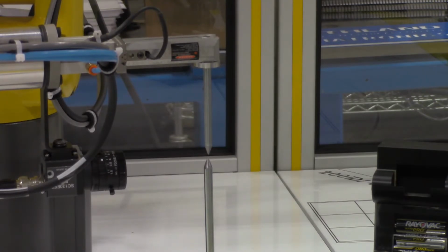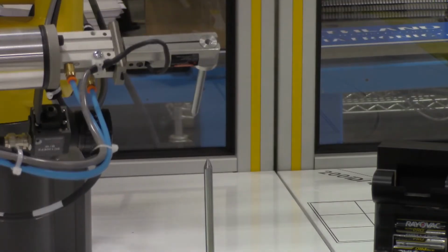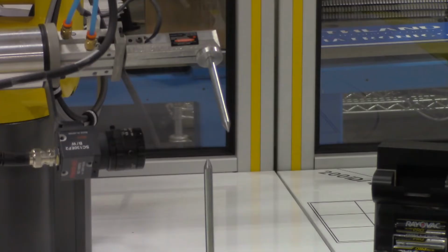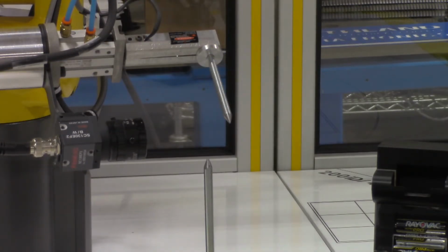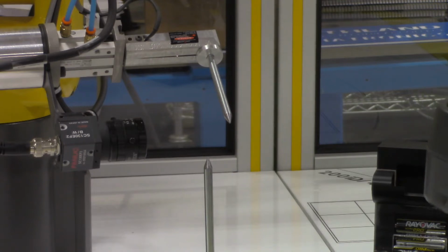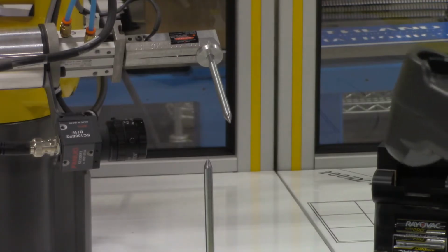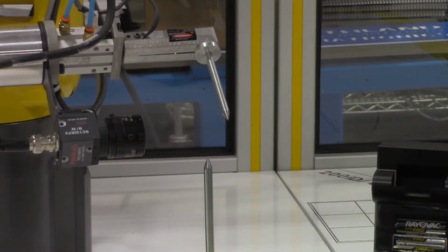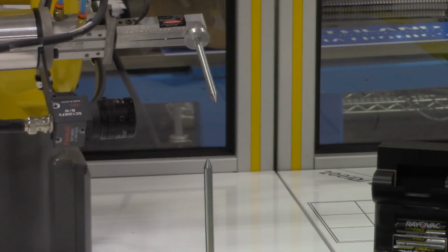Let's see. Actually, I'm going to move joint number 6. Okay. So I've rotated this a few degrees, and it may be hard to tell, but that's good. Now we're going to go ahead and change it back to world mode and line up those 2 points again. So we're going to go X minus, trying to get these 2 points to line up with one another again.